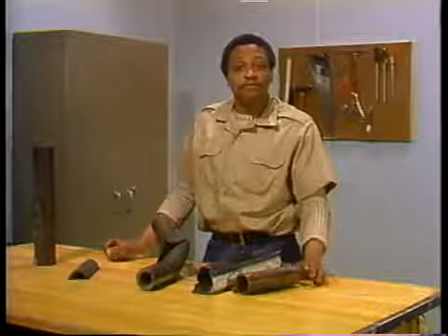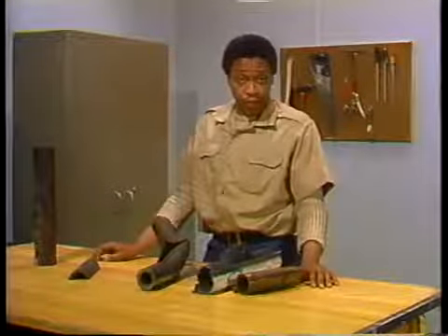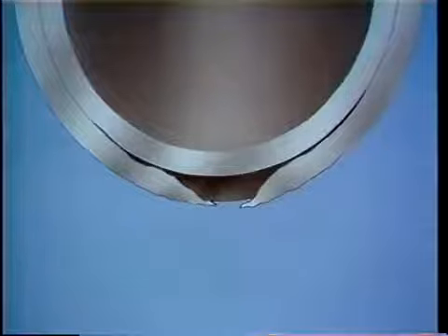Tube wall lamination is the most common example of material defects found in boiler tubes. A cross-section of a laminated tube looks something like this. The lamination, or layering, occurs during fabrication of the tube. It will appear as cracks or breaks that go partway through the tube.